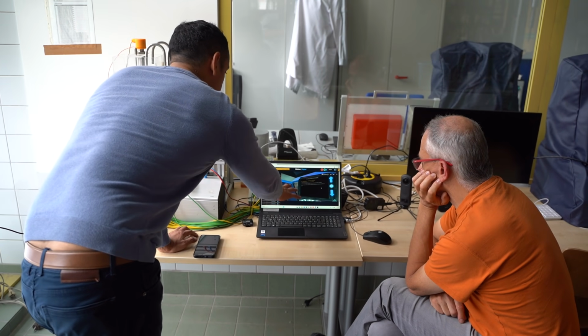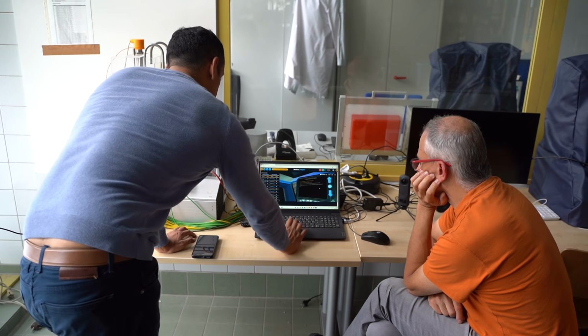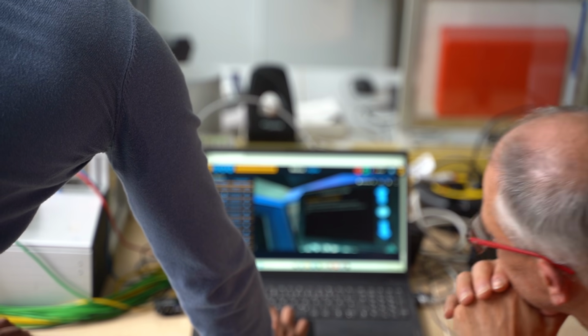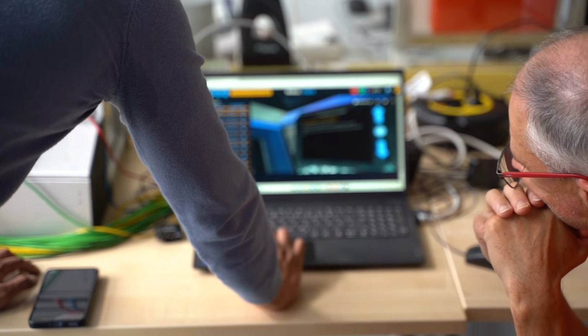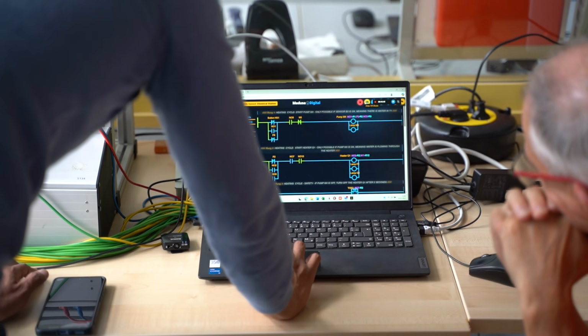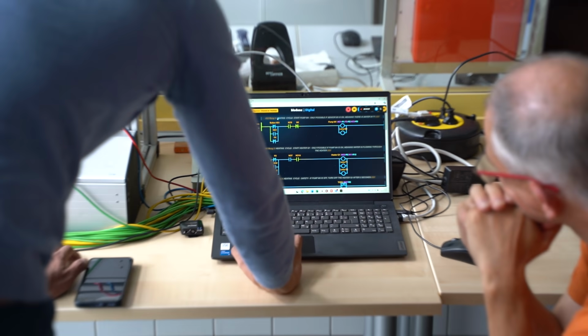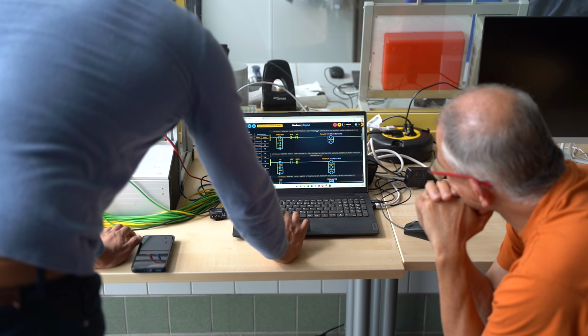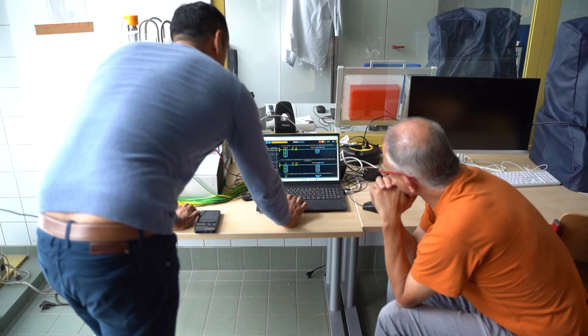Now that we are right now into the system here, with the computer, I can actually toggle exactly the same button here. The ladder logic for the heating system is rung number 1, heating cycle, start pump M4, only possible if sensor B3 is on, meaning there's water in T1.